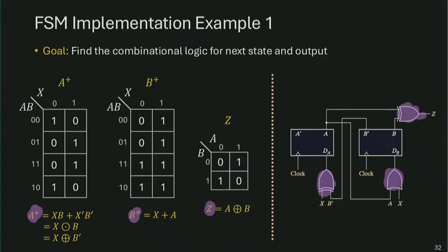Right. And the analysis and implementation examples that we solve here are for the D flip-flop, which is the most straightforward case. Because inside the D flip-flop, the next state equals D. So you don't have to do so much translation between specification and the implementation. For the other flip-flops, there's an additional layer of translation, which is a little bit more complicated. So that finishes our example of implementation analysis for two D flip-flops.